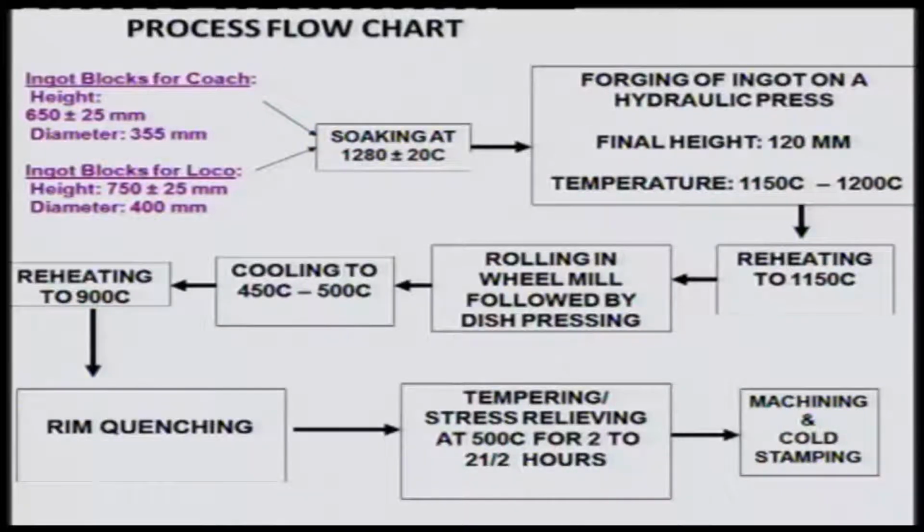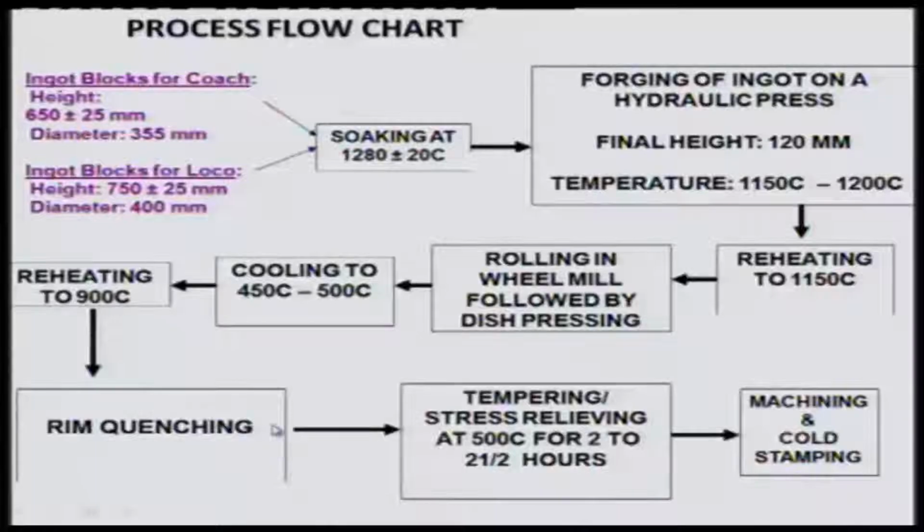Here again the objective is to produce a hardened rim, but not so hard that you produce martensite, you produce only fine pearlite, and it is possible because the structure is so large that achieving cooling rates to produce martensite is very difficult. So, you end up getting very fine pearlite on the rim, and then all of this quenching produces a lot of internal stresses. So, it has to be stress relieved.